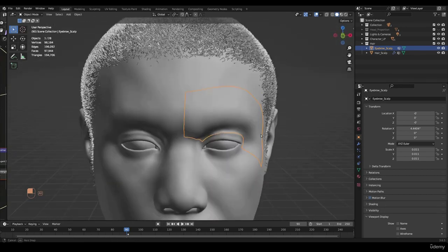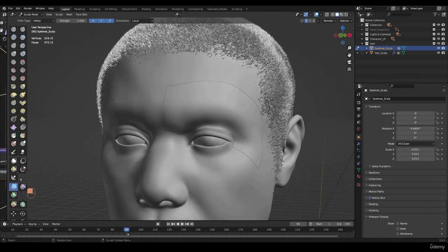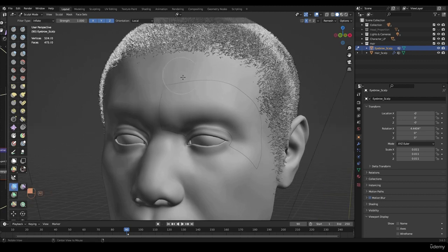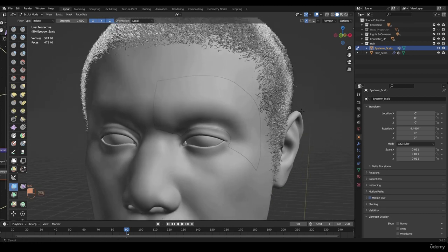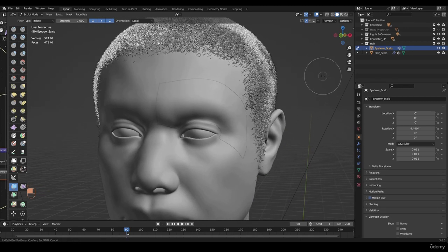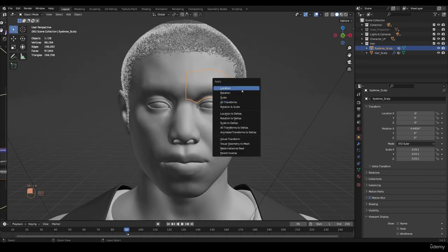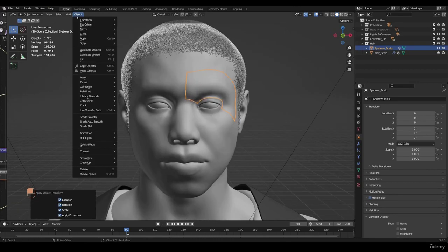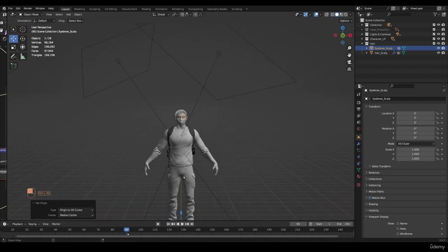And we could go Control Tab, go to our sculpt mode, and go to our filter here and inflate, and we could go ahead and scale it. Go ahead and just drag it down so it's going inside a little bit. There you go. Go to Object Mode. Now we need to Control A and All Transformation, and then make sure set origin to 3D cursor this time, because what we're going to do is we're going to mirror this on the other side. Let's go to set origin to 3D cursor, so then when we go to move tool, it's in the middle of the grid.